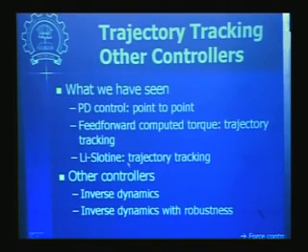Now let us just recap what we have seen so far. We initially started with the PD control, point to point control or regulation result. So PD control for regulation purpose, to move a manipulator from one point to another point. Then we introduced feed forward computed torque strategies, basically for trajectory tracking applications. We didn't do much analysis of these, but we have seen that these controllers will result in better tracking performance than just a PD controller.